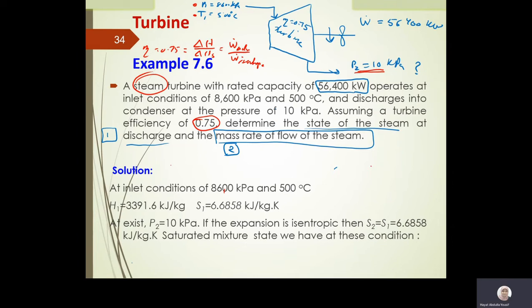Okay, so that's basically the efficiency. The good news is that I have the efficiency. I don't have here other than one information, but we can do the following. Listen carefully. Since I have the efficiency, why don't we get delta HS? And delta HS means what? Means delta H based on isentropic. I know my process is not isentropic, but when I get delta HS, I can use this relationship to get the actual delta H. Okay?